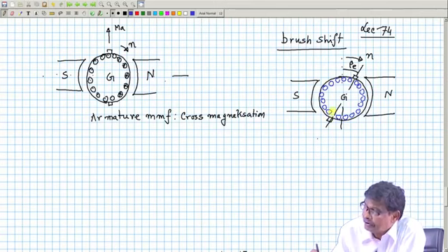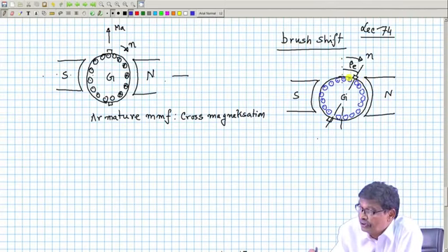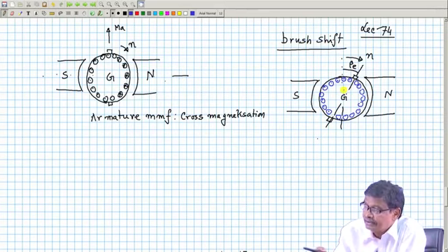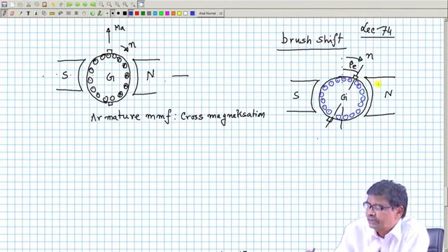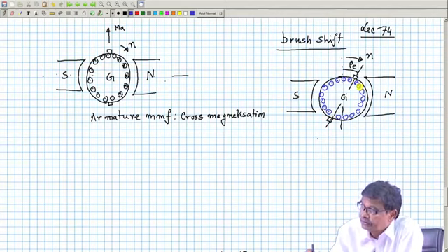However, the currents in the conductors are all in series. So, up to this point it will be dot. The induced voltage here is once again dot, in this portion I am confident dot dot dot, but the current is delivered by the machine, and a few turns which are going under north pole influence have to carry the same current. Similarly, currents here will be cross.